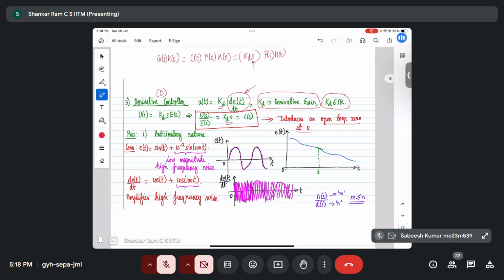But the point is, that's why it brings an anticipative nature. We will look at that shortly. We know that proper transfer functions are associated with causal systems. Causal systems are non-anticipative. So when we do not have a proper transfer function, that corresponds to an anticipative system, and that's what the derivative control is. The derivative control anticipates what is going to happen, and then takes corrective action.